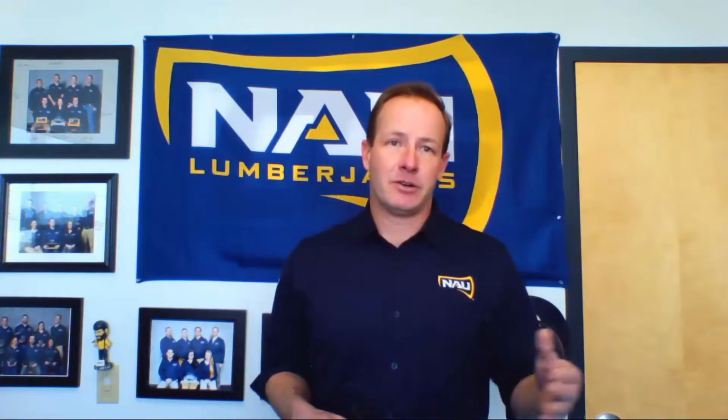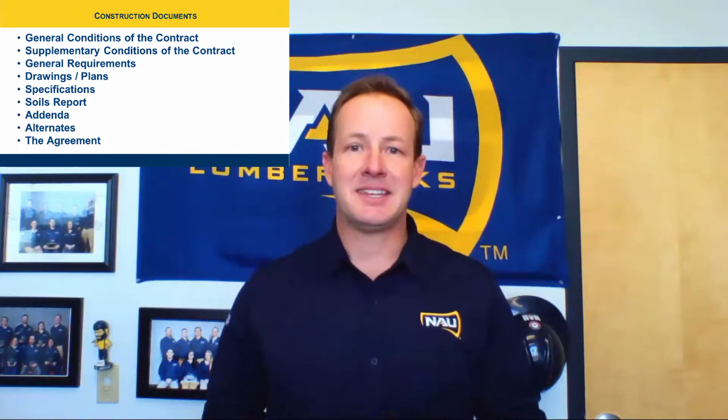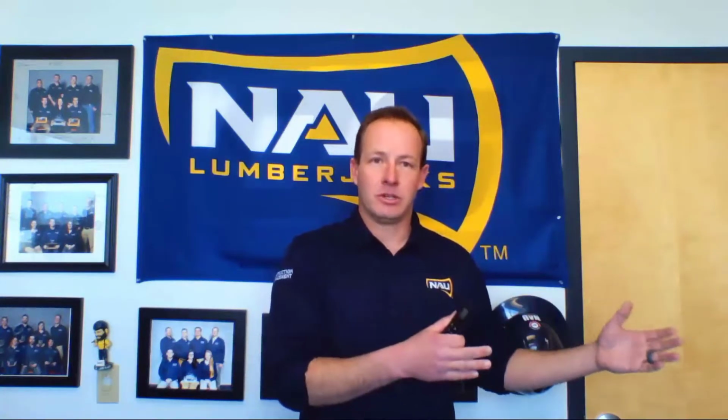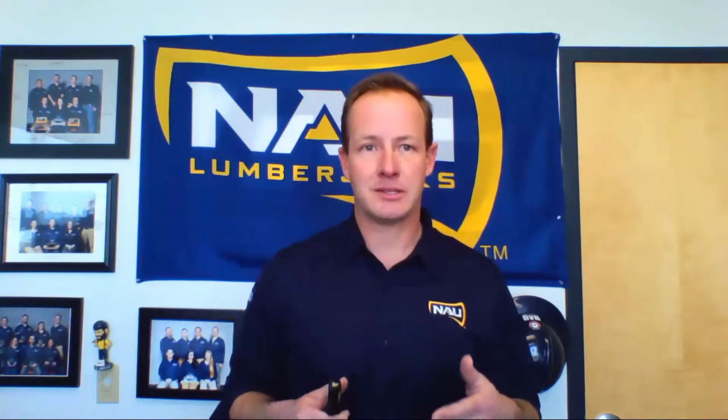The supplementary conditions of the contract are anything that's added to that, additional provisions and modifications of the general conditions. So anything that wasn't in the normal general conditions, they're going to put into the supplementary conditions. So just as important as the general conditions, you need to know what's in the supplementary conditions.